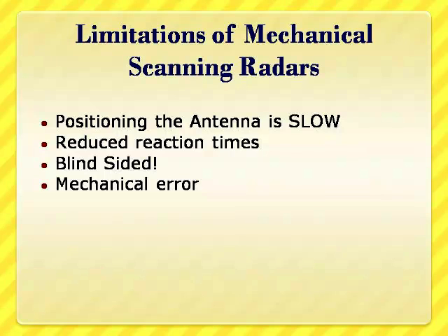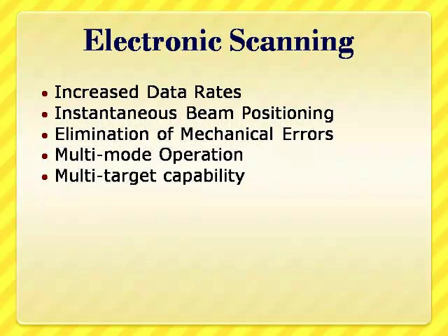That means the antenna beam is going to be steered to different locations by electronic means and hence achieve the electronic speed of movement, that is 3 into 10 power 8 meters per second theoretically. So let us see what will be the advantage if we switch over to electronic means of steering the antenna beam of a radar system.